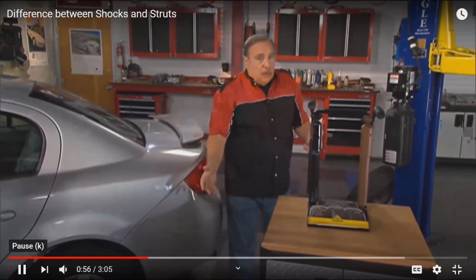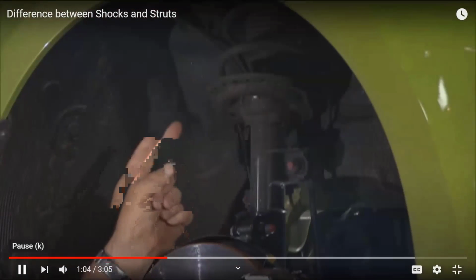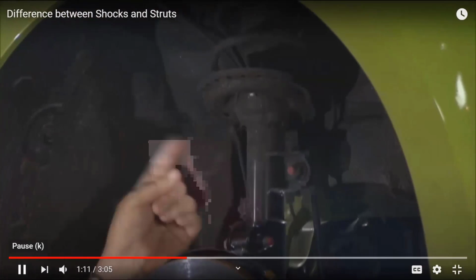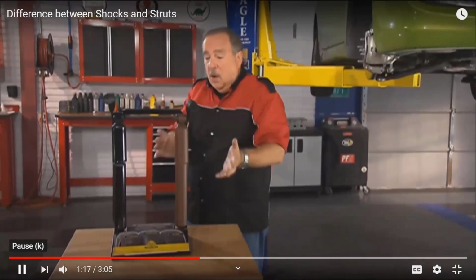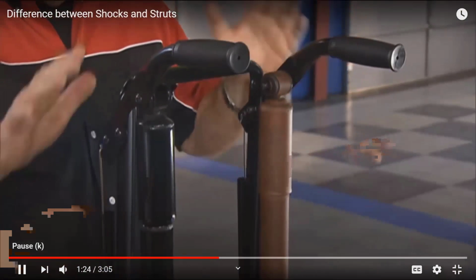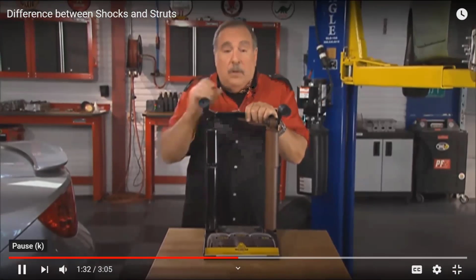But what's the difference between a shock absorber and a strut? Well, here we have an example of a strut. Now, what this does is it has a shock absorber in the middle, and then around it, it has a spring to support the weight of the vehicle. A shock absorber, on the other hand, such as we have here, these shocks do not have the springs on them. They have nothing to do with the height of the vehicle or anything like that. The only thing they do is to keep the car from bouncing. The spring is mounted someplace away from the shock.